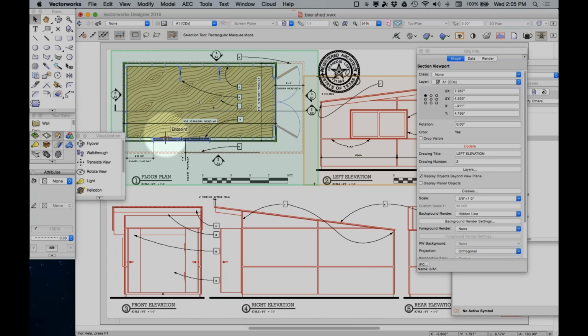So in other words, to answer that question, I wouldn't do a framing model that was extremely detailed in schematic design unless it happened to be a single component. For example, I've done framing models of flat roofs in the past where it was really important to work out the structure early on in the design, because if it wasn't structurally feasible within the budget, we were going to go in a completely different design direction. So just because you do a framing model of part of the project doesn't mean you have to do a framing model of the entire project. Hopefully that starts to answer that question.